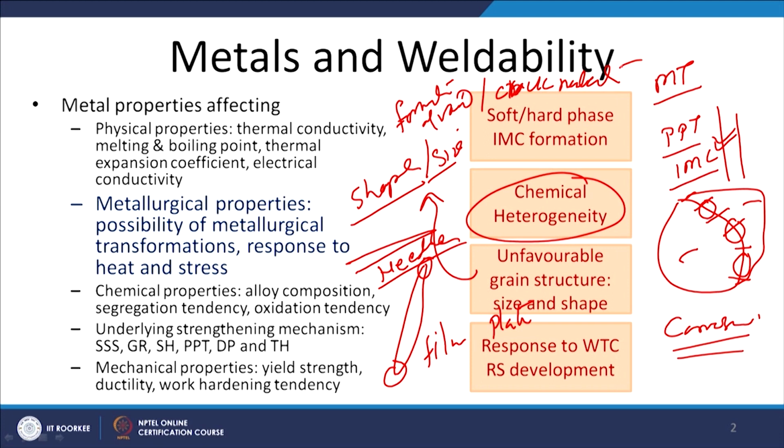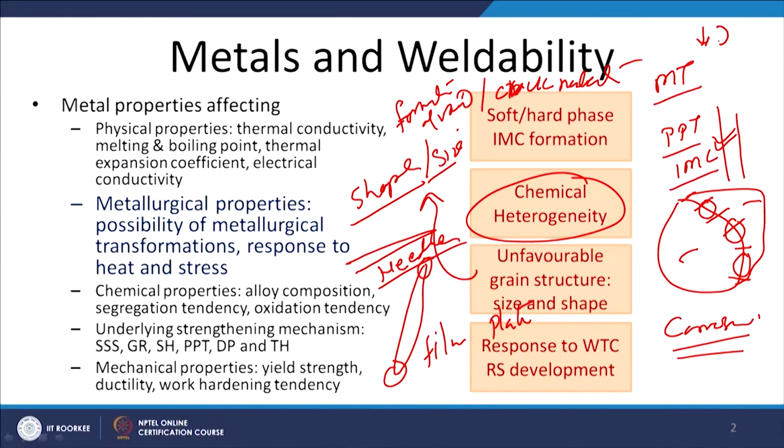And so, if such precipitates and intermetallic compounds are being formed having a higher aspect ratio, with needle-like or plate-shaped structures, which will be promoting higher stress concentration at the particle matrix interface, then that in turn will be reducing the ductility, the toughness, and also the fatigue resistance of the weld joints.